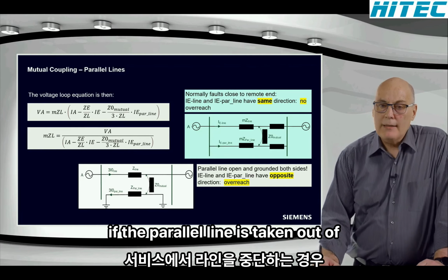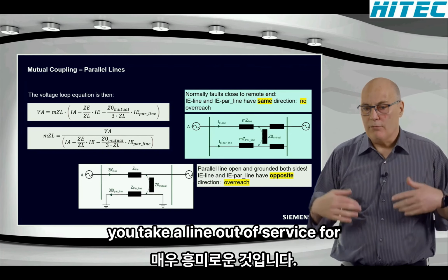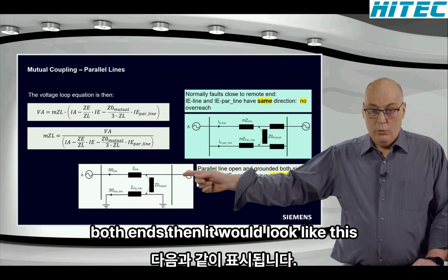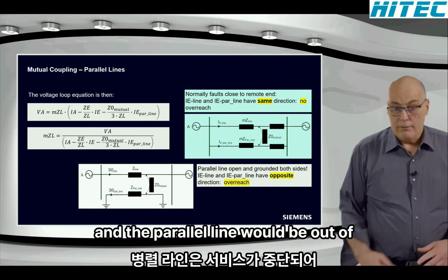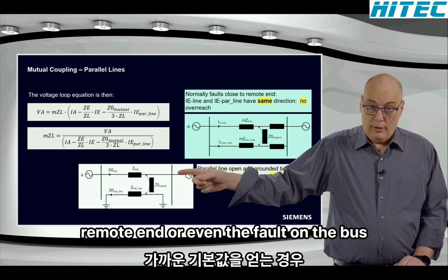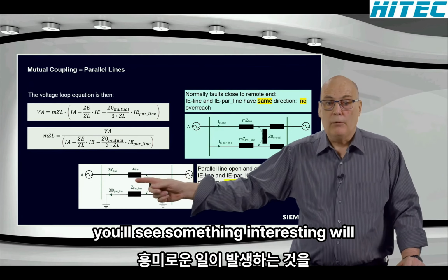If the parallel line is taken out of service and grounded at both sides, if you take a line out of service for maintenance work, etc., you would typically, for safety reasons, apply a ground at both ends. Then it would look like this. The protected line would be in service, and the parallel line would be out of service and grounded at both sides. If we now get the fault close to the remote end, or even the fault on the bus bar here, which is the critical one, then you'll see something interesting will happen.